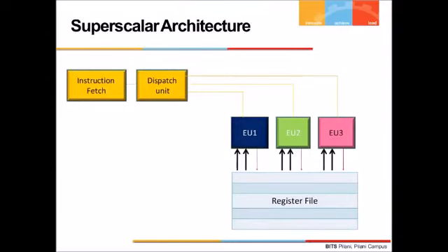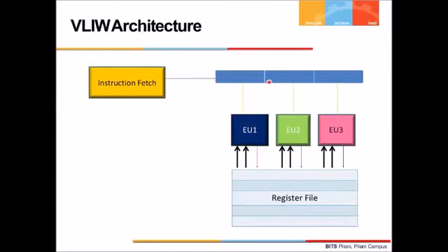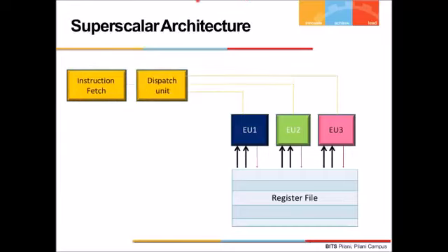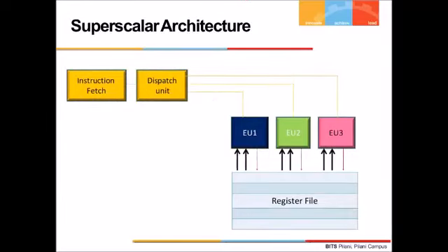There is one more type of fast CPU architecture, that is called superscalar architecture. It is similar to VLIW architecture. Here also there are parallel execution units. The only difference is that the instruction words are also different. So separate instruction words come and they get decoded and dispatched to these execution units. Whereas in case of VLIW, there is only one instruction word, and that instruction word is getting decoded properly. Here, each instruction separately comes and is executed through separate execution units.